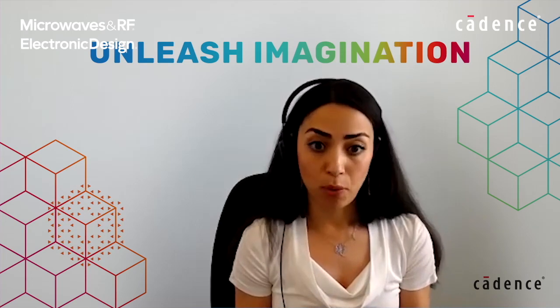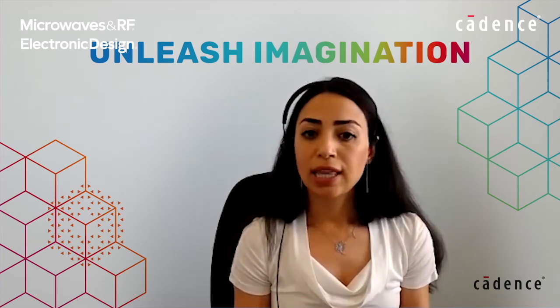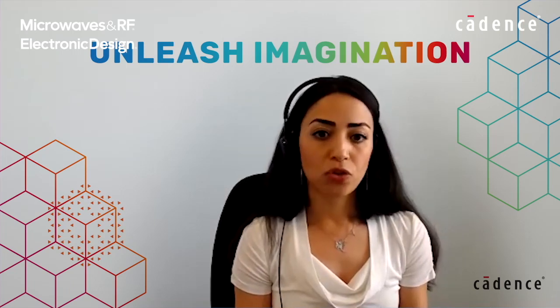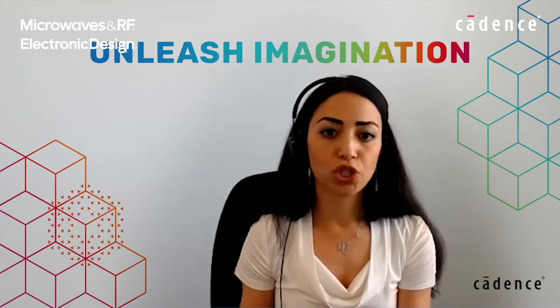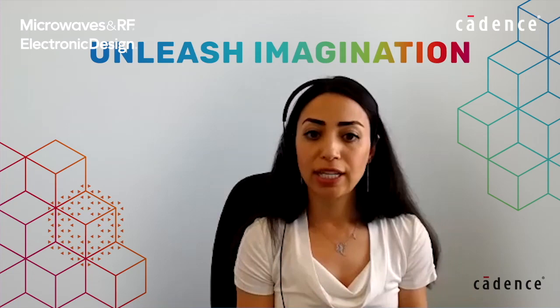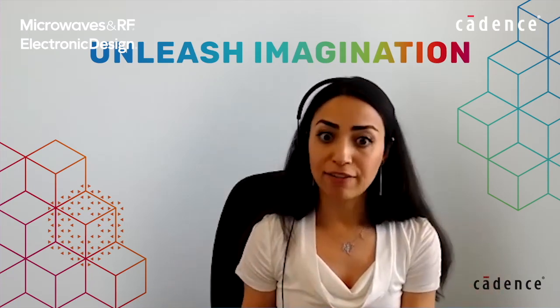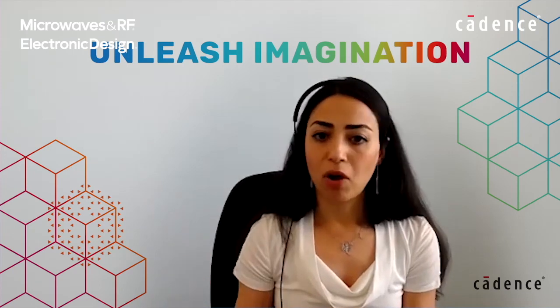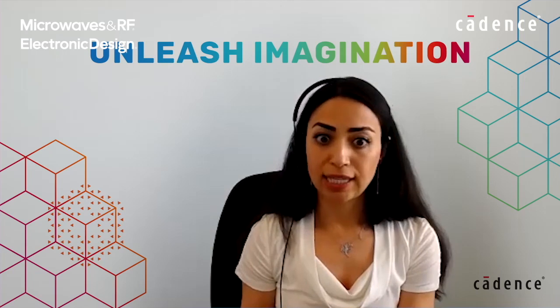And that's very important when you want to do your dynamic IR drop analysis. Now, let's say that you want to optimize your thermal performance in an entire system, which has an enclosure, fan, then Celsius automatically generates a simplified model from the FEA, and you can bring it into the CFD. And we have design models like fan, heat sinks that you can import and do your CFD analysis.